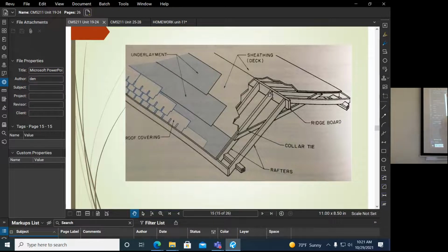So on top of the sheathing, there's underlayment. We now use rolls of 50-year plastic sheeting, which lasts a lot longer than the felt paper that used to be used. There's a couple of grades of felt paper: 15-pound and 30-pound. Some people used to use the 15-pound, really cheap stuff, throw it out there, and then put the shingles on it. But that fails after 20 years.